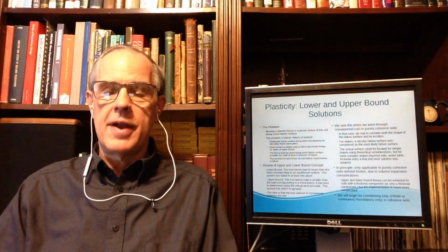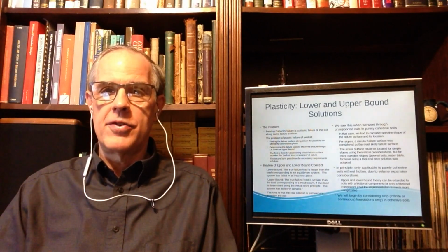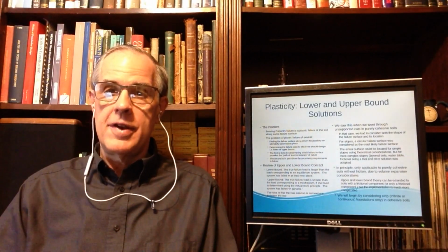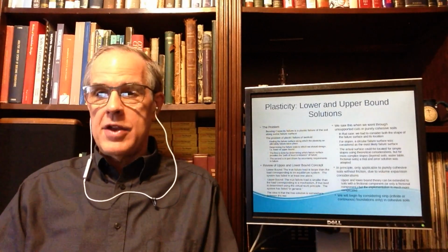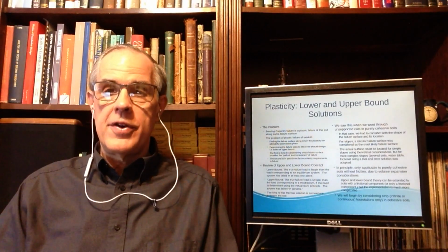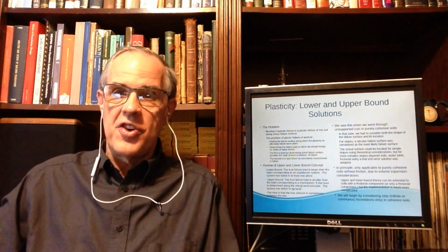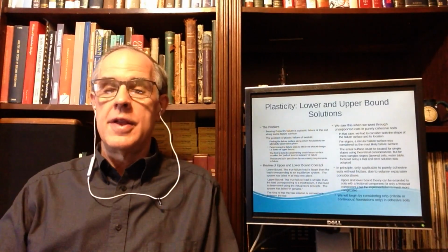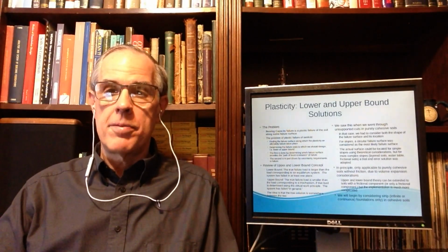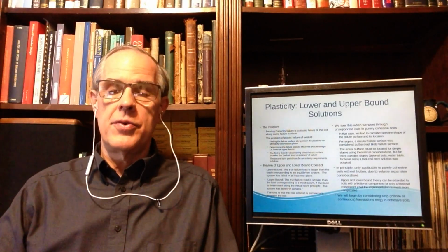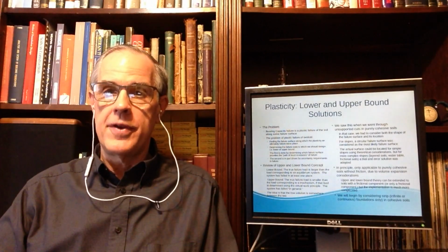Sooner or later, you're going to have plastic deformations or permanent deformations. Sometimes those deformations can be relatively small. In the case of bearing capacity, they tend to be relatively large and catastrophic, because what you're dealing with is shear failure. And total shear failure is plastic failure. Not just deflects in shear, but actually gets past the elastic limit and gets into the purely plastic zone. And as I said in soil mechanics, we're going to go into this assuming a Mohr-Coulomb theory of failure with elastic, purely plastic failure.